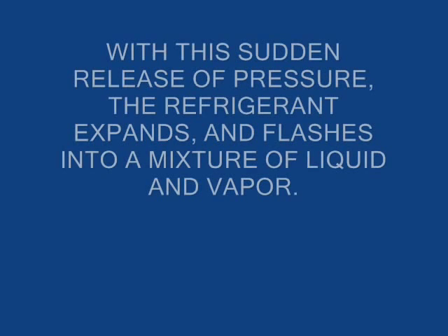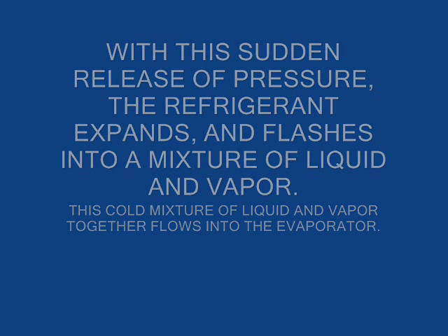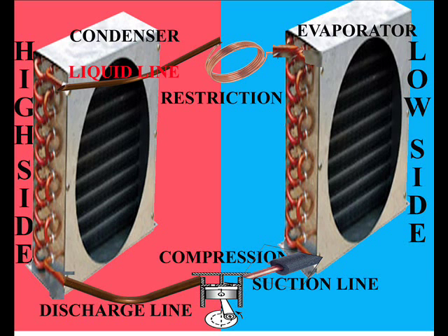With this sudden release of pressure, the refrigerant expands and flashes into a mixture of liquid and vapor. This cold mixture of liquid and vapor together flows into the evaporator. The cycle then repeats this sequence over and over again.